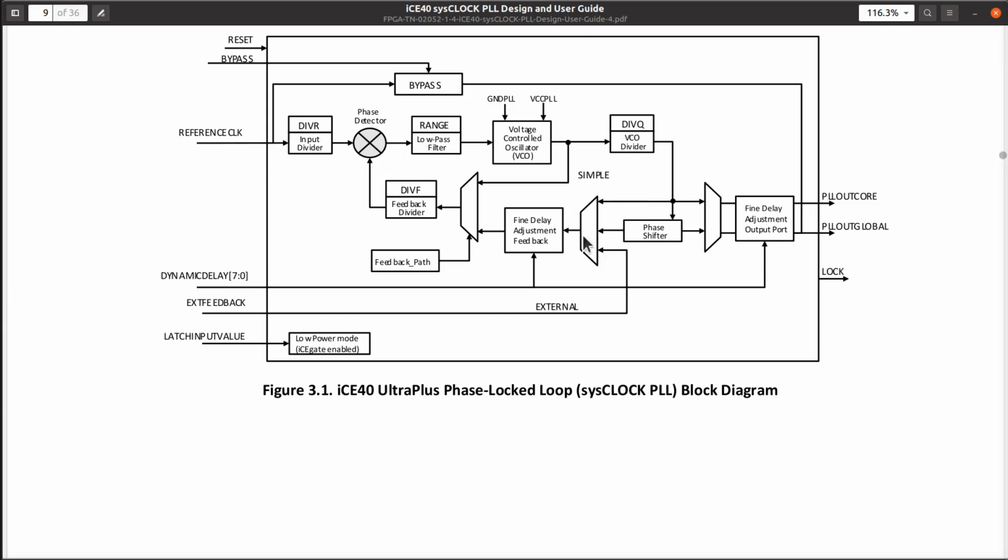The point is, you can set this so that the leading edge of your clock, relative to the source over here, can happen earlier or later in reference to this reference clock, so that you can cause various delays and timings and the order of operations to happen in an absolute known way, if you get into a design with super fine details and needs for that kind of tuning.